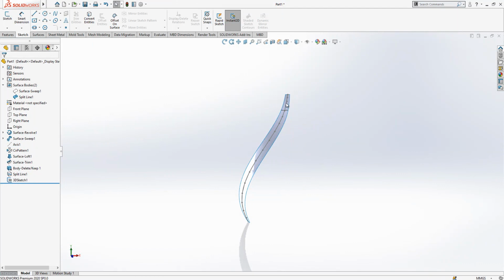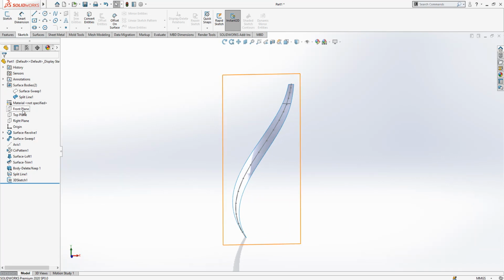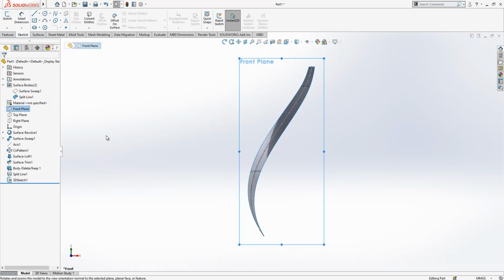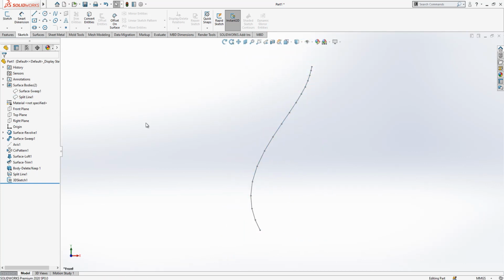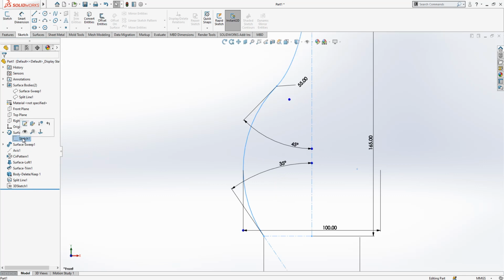So simply we break this line into the pieces, because we don't have in a SolidWorks in a way that we could create an equal distributing length, but we have a segment which divides in equal parts. And after this operation, now we did, I think, most important thing. The rest will be very easy. We look normal too. We can hide this split line and the 3D sketch, and we can create our solid.